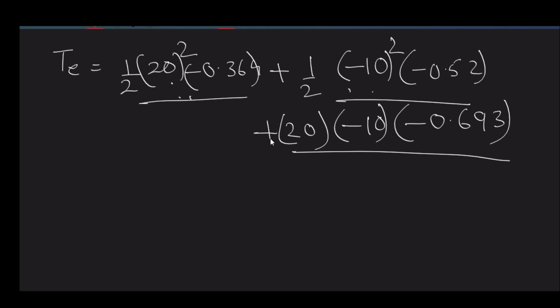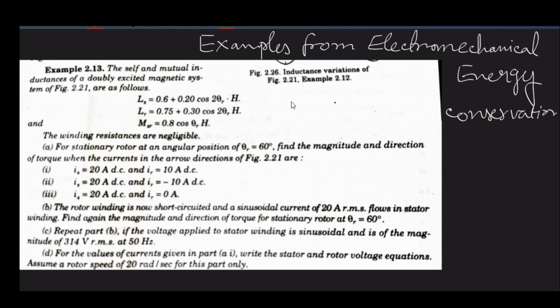Here you can see that if this one can align the rotor along this axis, then obviously the first two terms, giving you the negative term, will be able to align it, and by aligning it, it can reduce the reluctance of the path, reduce the air gap, reduce the size of the energy reservoir, reduce the total energy stored in the system. So reluctance torque is always the same irrespective of current direction.